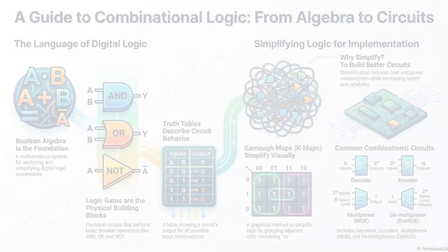Right, and that introduces some important jargon. Each of those product terms is called a min-term. Yep. And when you list all the min-terms that give you a one output, that's called a canonical form. So when you see a designer write something like F equals sigma M 3, 4, 5, 6, 7, it's not meant to be cryptic. It's just shorthand. It's saying the output is 1 when the input combination matches row 3 or row 4 or row 5 and so on. It's a compact way to describe the whole table.